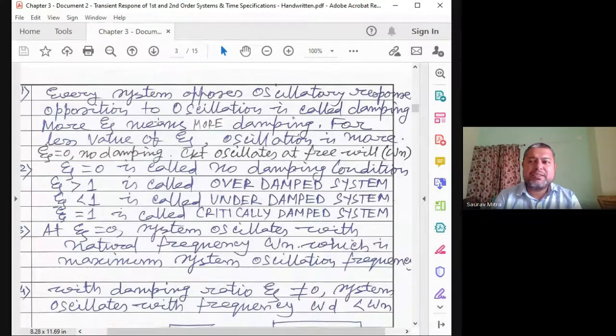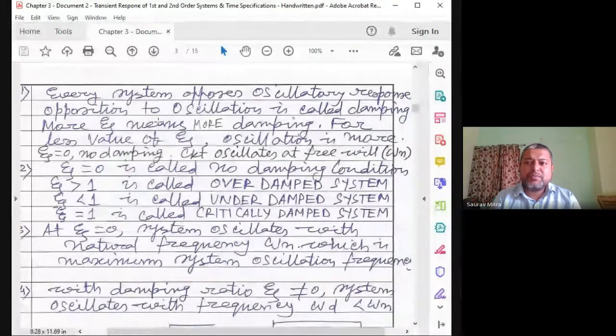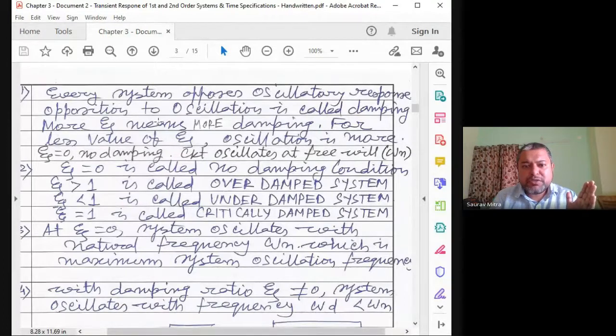So system gain is K. System gain is something which actually decides what is going to be the pole position. If system gain K is very less, in that case poles are too deep into the j omega axis. Then we started increasing the value of K, and in that case we find that poles are shifting towards the right side. So the more the value of K, system poles will shift to the rightward side of the j omega axis, and that means poles have started becoming unstable.